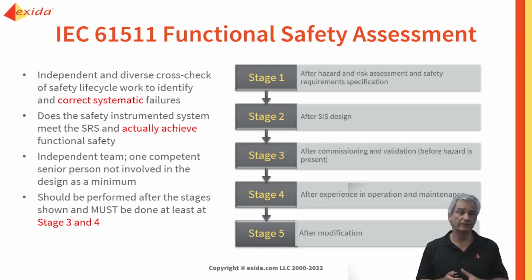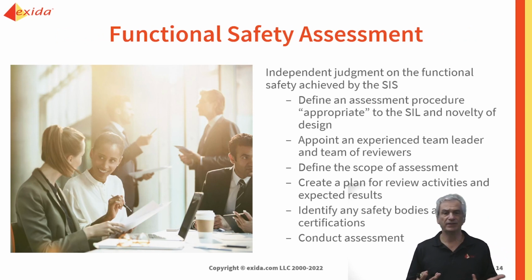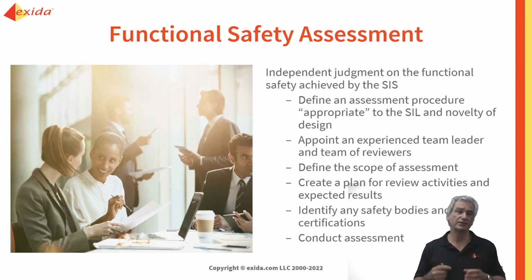And as I say to the classes that I teach, these are there for a reason, so we should follow them and do them. But unfortunately, many clients I speak to haven't done a stage 1 FSA, haven't done a stage 2 FSA, and even in some cases clients are asking us to do stage 3 months or even years after they've been operating. So in the functional safety assessment, the process is that we are doing this independent judgment on safety. So we need to define a procedure that's relevant to the SIL that we're trying to look at and the novelty of the design.